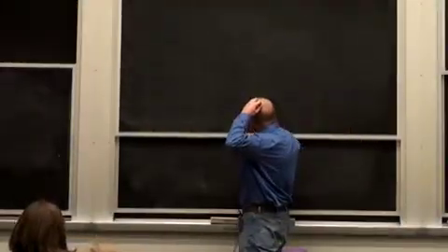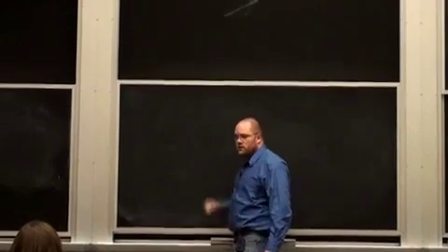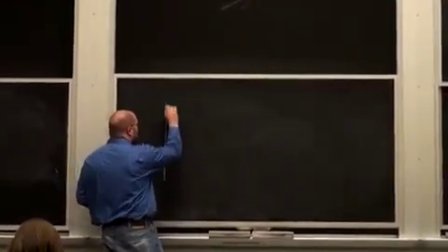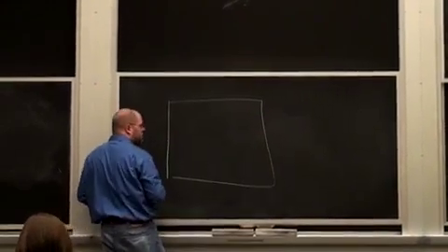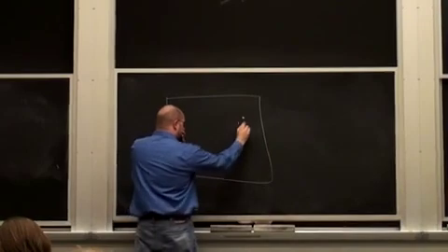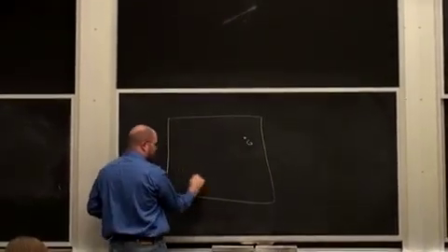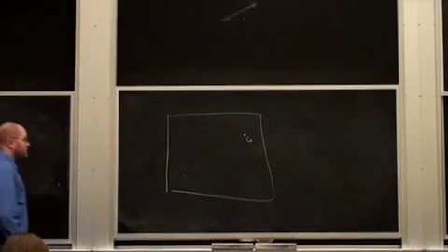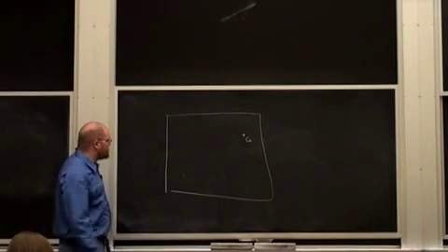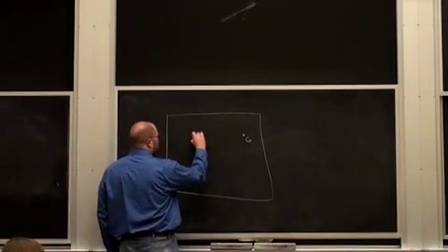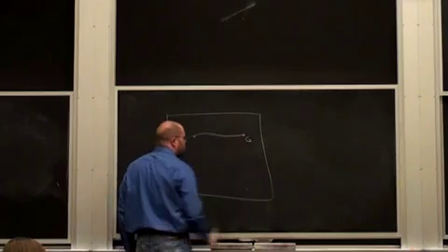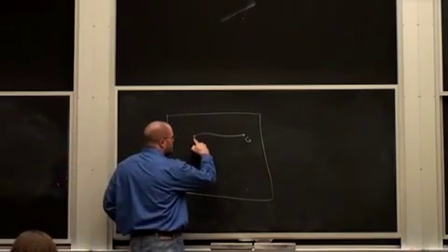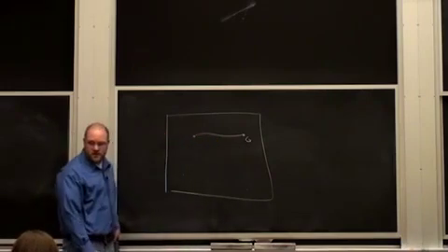Okay, let me say the big idea is, for LQR trees again, and you can tell me where you want more details. So here's the basic story. I've got some goal I want to get to, and I'd like to be able to get there from every initial condition, let's say. So the idea was we know how to stabilize trajectories. So let's just pick a point at random, design a path to the goal like that. Design the LTV, LQR stabilizer on this.